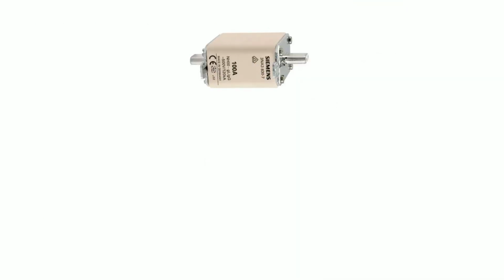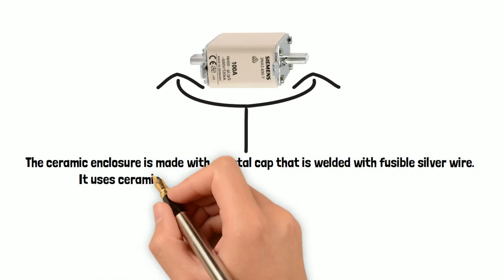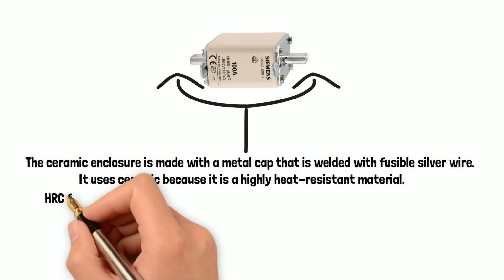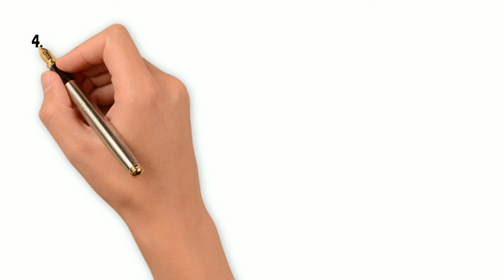At both ends of the fuse, the ceramic enclosure is made with a metal cap that is welded with fusible silver wire. It uses ceramic because it is a highly heat-resistant material. HRC fuse is consistent, and it has the feature that if there is a high fault current, then the break time is low.